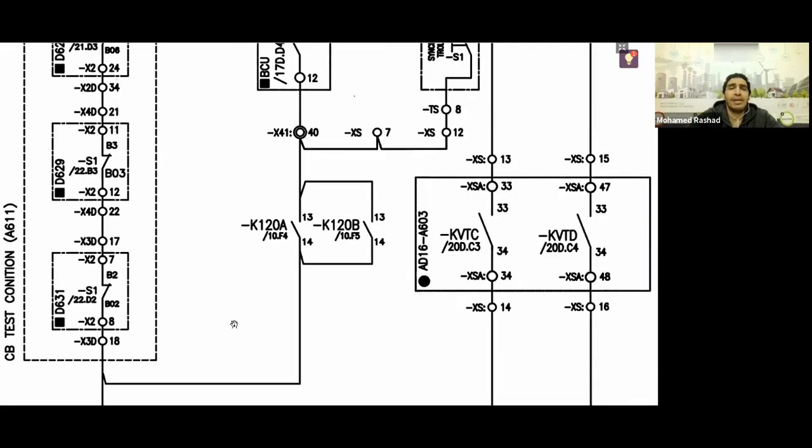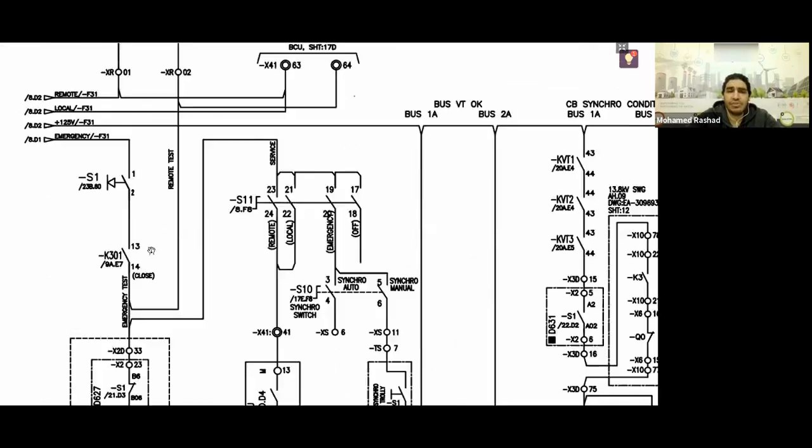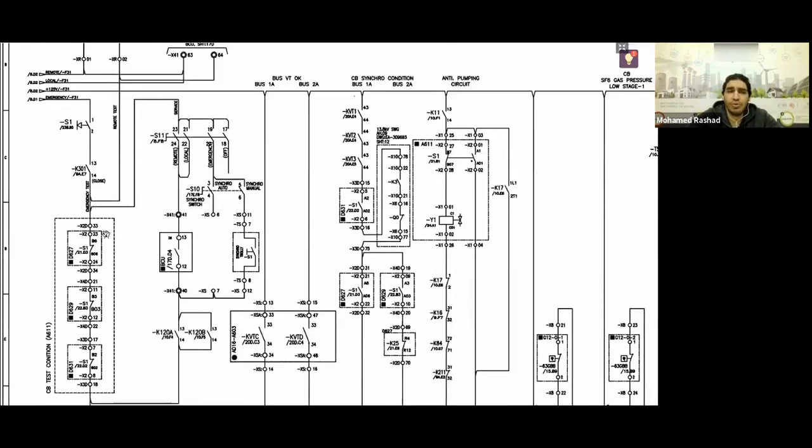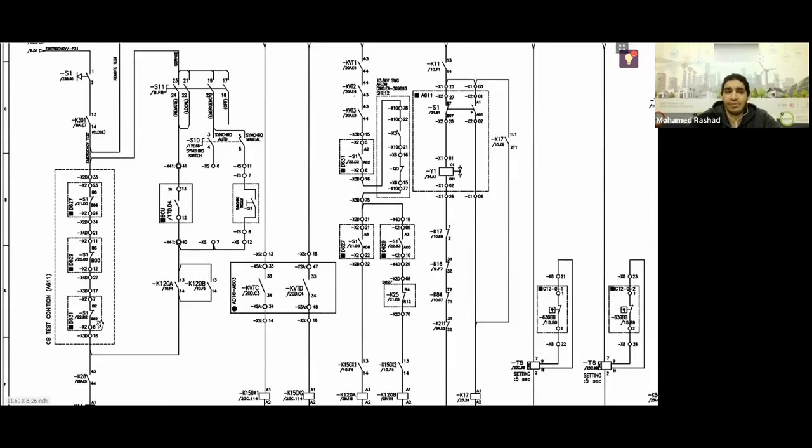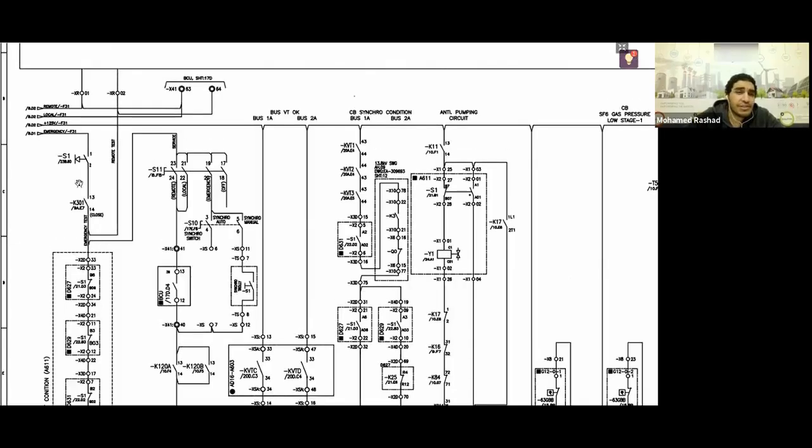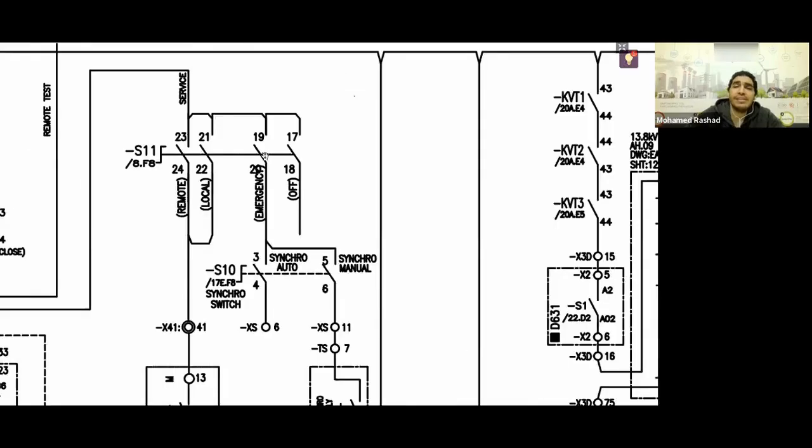Great, okay. And then I come to this point, where I am in emergency, local, or remote mode, and you have the 3 knives or 3 switches open. I went down to our level, all right. At the same time, engineer, I now have a branch coming out here as well, all right, my dear. What does this branch say? Focus with me. This branch, if you go to it like this, you will also find the same selector switch, taking another contact from it here as well: off, emergency, local, and remote. The off is not used for anything, but you have emergency, local, and remote.